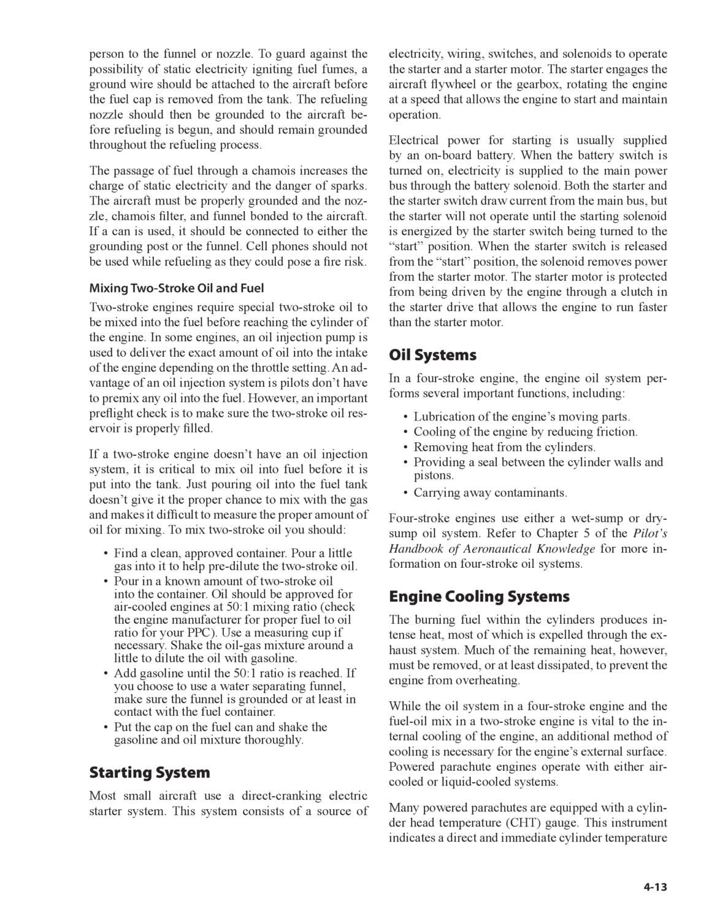The aircraft must be properly grounded, with the nozzle, chamois filter, and funnel bonded to the aircraft. If a can is used, it should be connected to either the grounding post or the funnel. Cell phones should not be used while refueling as they could pose a fire risk.